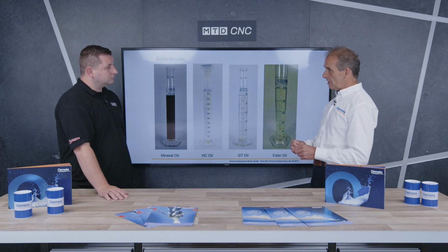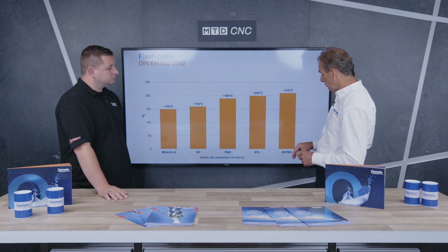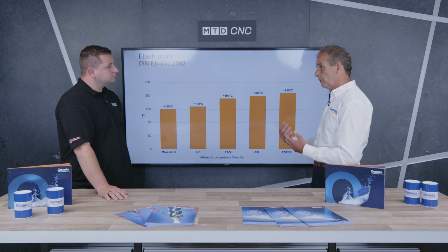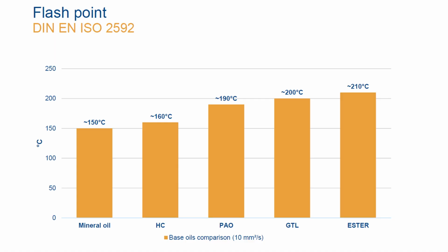In terms of performance levels, one question that we always get asked is flashpoint. Is my product going to catch fire? This is obviously very important because people have insurance to pay, they have expensive machines, there's a lot of fire extinguisher equipment that they need to fit. So when you look at the graphs here, and these are all DIN standard tests on flashpoints, you can see again the GTL oils and the ester oils significantly more improved on the flashpoint than the mineral oils. So a huge safety advantage in taking a look at these ester and GTL oils.